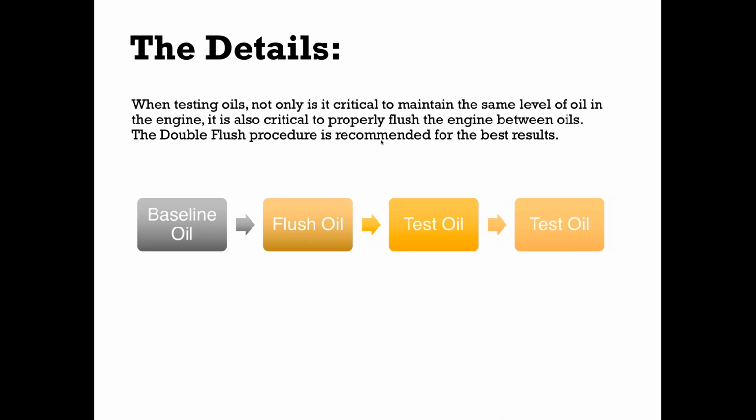And they said, what do you mean? I explained to them the double flush procedure you're looking at on the screen right here, and said, by the way, you gotta make sure you check the oil level so that you're only putting in the amount you need. And they went back and ran that same test again with the same oils, but changed the procedure, used the double flush, used the level measurement to dictate the volume of oil put into the engine each time, and the results were completely different than the first time. And that was, again, a good example of an eye-opening moment for them: oh, okay, there's a lot more to this than we realized that can guide you along the right way.